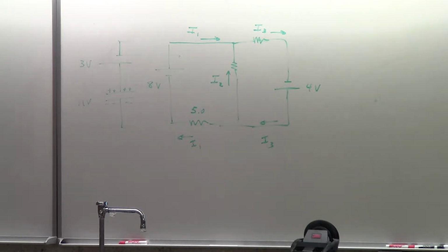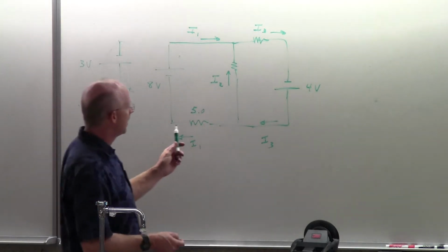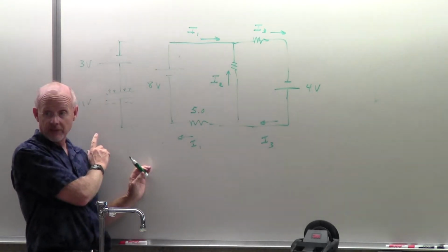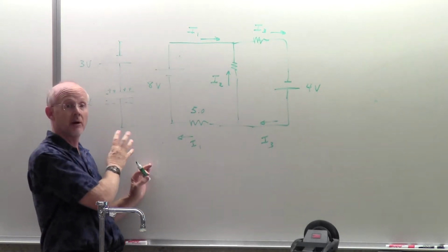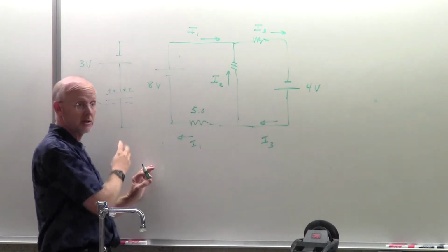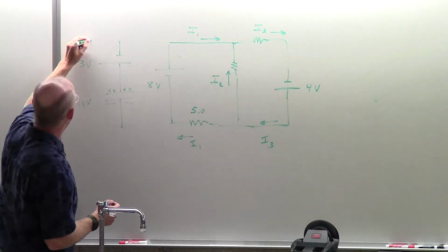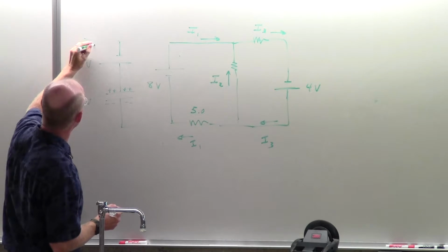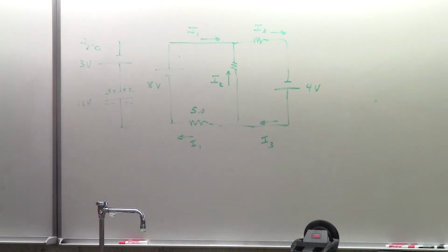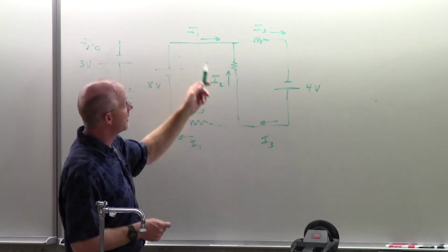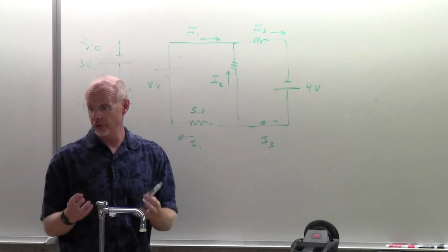All right, so doing this circuit, I do want you to see, isn't it a lot simpler now that we've taken this part off? That was an important and useful step here: separating this off, realizing it's already charged, solving for number E here and finding out what the charge is, and then answering the question of the current in that part of the loop. The current in this part of the loop is 0. So we can just quickly say there's no current in that part of the loop. And now I have 3 unknowns: current 1, current 2, current 3.